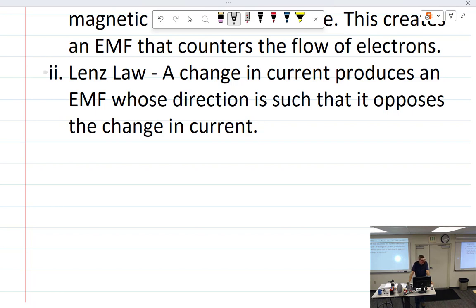So what do we have with AC? Constantly changing voltage, constantly changing current. So the current goes this way, it goes that way, it goes this way, it goes that way. So Lenz is basically saying that this change in current, that change being a build up, a build down, going the other way, coming back up, every little bit of change that it creates is a field change that creates a magnetic field that makes it so that the change shouldn't happen. It's resistance to the change.